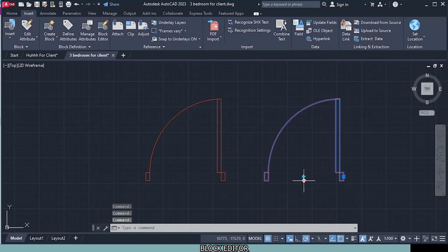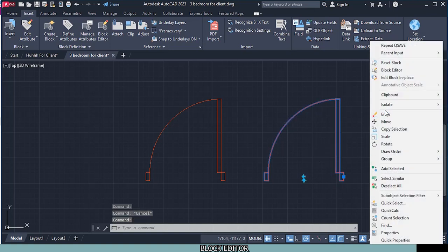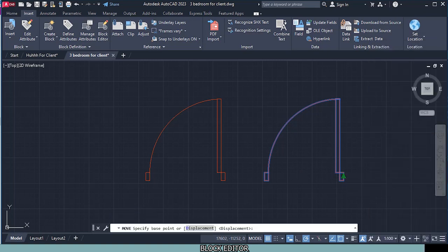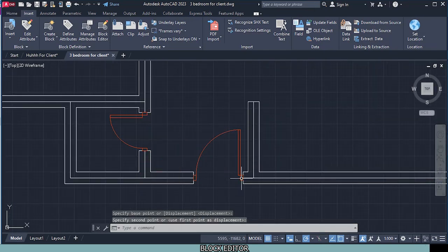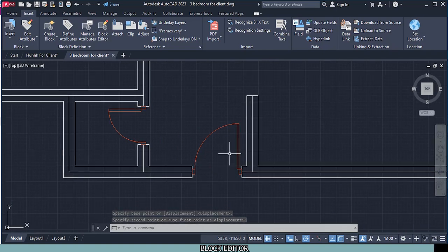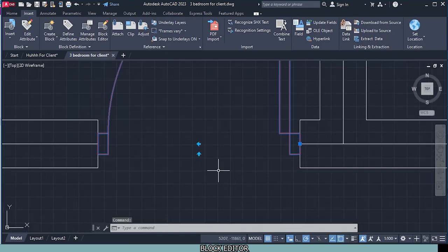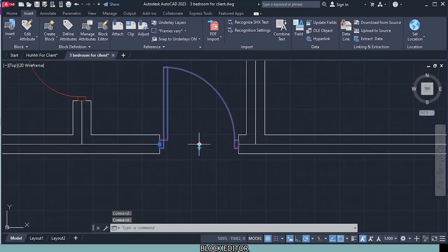So let's just copy this one, since we only have one main door, one 1000mm door in our building. So I'll just click it, move it, click on this midpoint and drop it right there. This is how I want it to be swinging. But if that's not the case, I can easily just select the door and click to flip it, click to flip it.